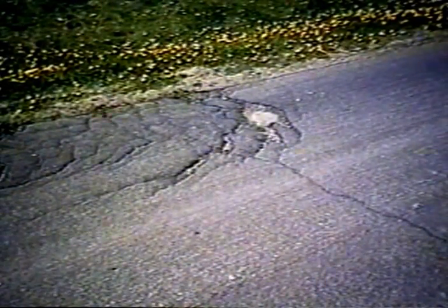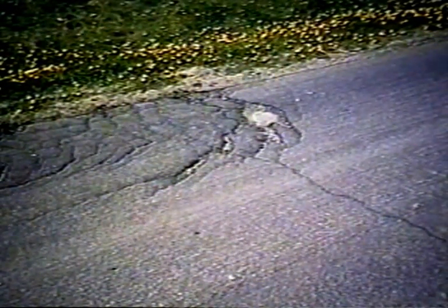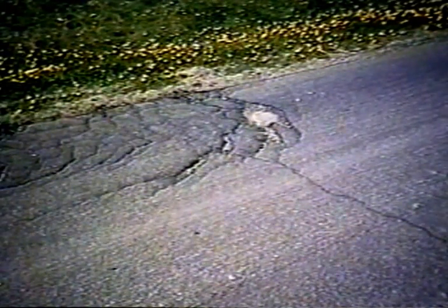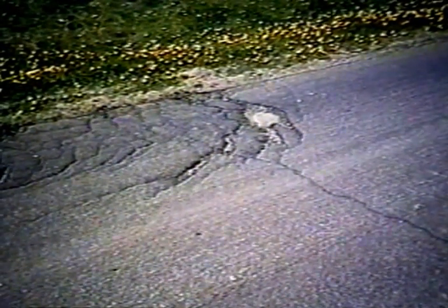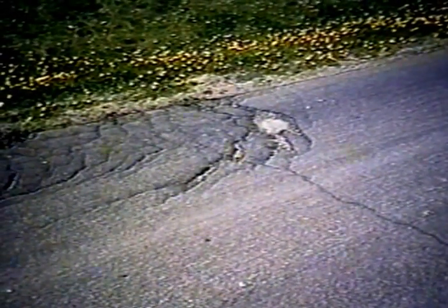Another example of slippage cracking, and it's characterized by kind of crescent-shaped or rounded cracks. Oftentimes you'll see this near a stop sign where traffic is braking or accelerating, and it tends to pull those two layers apart. The prevention for this kind of problem is to apply a tack coat on your overlays so that you get better bonding between one layer and the other. Or if you're putting an overlay down and the surface is dirty and has mud on it, then you're likely to get this kind of slippage cracking. It doesn't indicate a strength problem with the pavement. It simply means that you have had one layer slide on top of another.